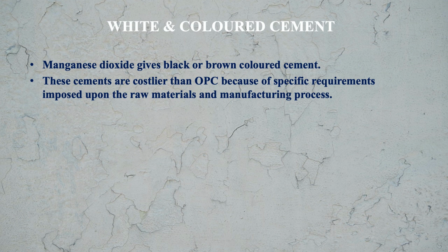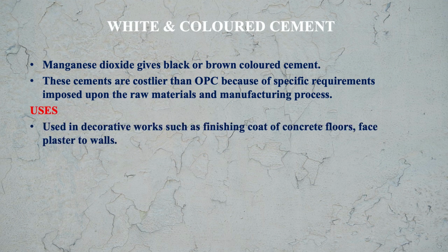What are the uses of these cements? These cements are used in decorative works, such as the finishing coat of concrete floors. If you want a colored concrete floor, then you can use colored cement. Then face plaster to the walls: if you want colored walls, you can use the colored cement in the plaster.